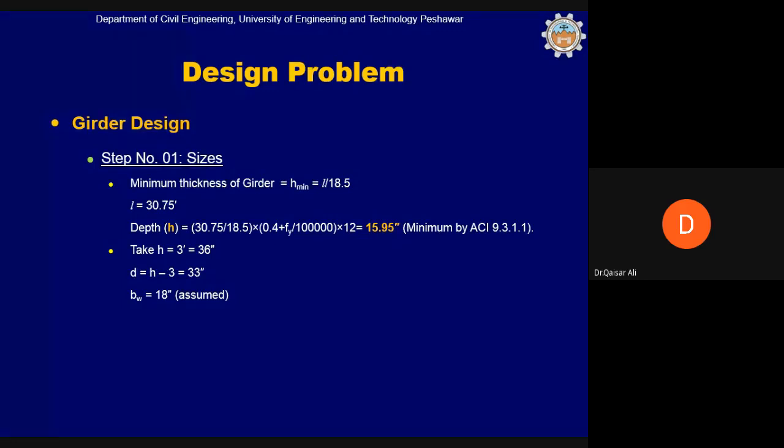In all these lectures, we are not doing this, because the calculation of deflection will open another area of discussion, and it is beyond the scope of this course. So we are not discussing all those deflection steps. If you are interested in the deflection calculation, again, in my MSc lectures, you can find the serviceability lecture, which contains all necessary steps to calculate deflections. The calculated deflections can then be compared with the permissible deflection, and only then you will be able to see whether the assumed depth is correct or not. Here in this case, we are not doing this.